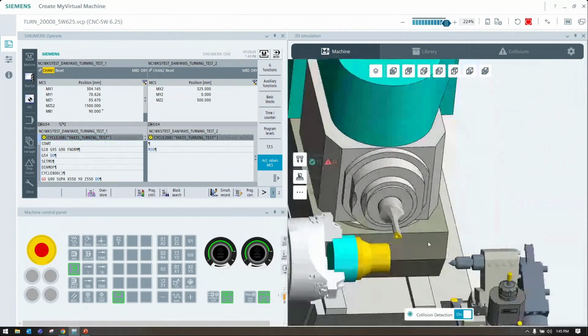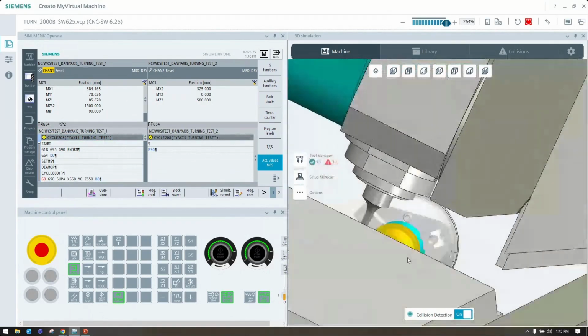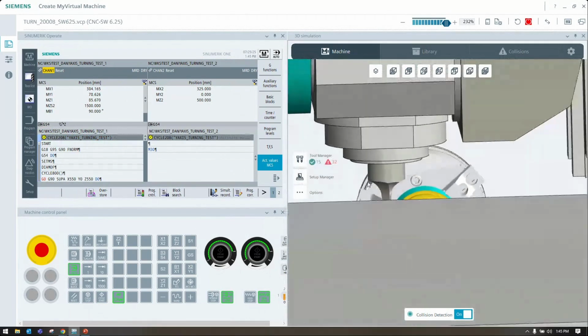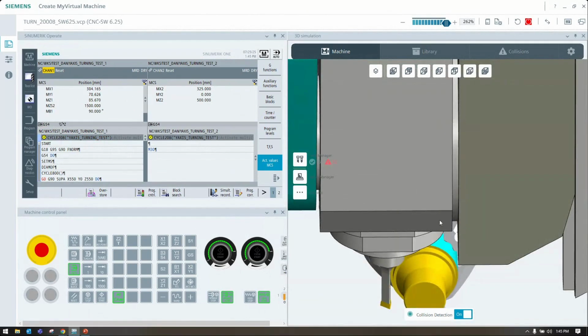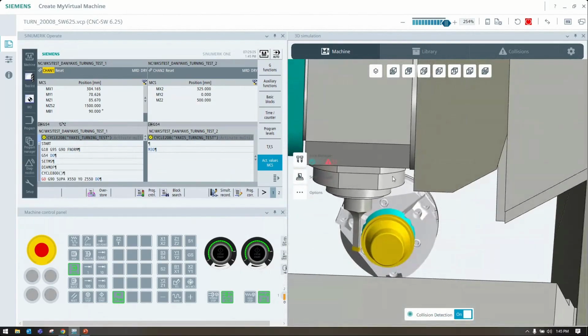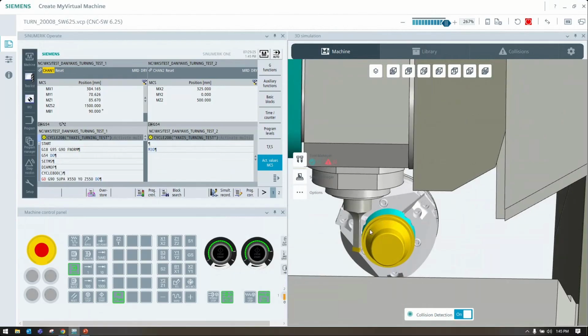So if we look at this, our tool holder length with respect to how much Y-axis travel we have is going to be the reason why we have a limitation on size of part, because at the end of the day we can only get so long with the tool, and we can only get so far with the Y-axis travel. So that's going to be the real limitation of it. I think to this point, this is one of those big limitations.